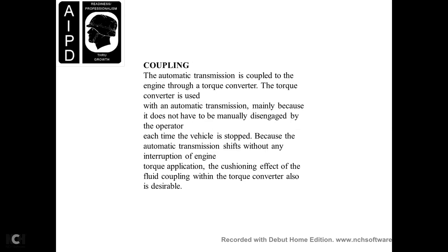Coupling: the automatic transmission is coupled to the engine through the torque converter. With the torque converter, the operator does not have to manually disengage the transmission each time the vehicle stops. To shift the automatic transmission without any interruption of the engine torque, the fluid coupling of the torque converter provides a cushioning effect as desired.